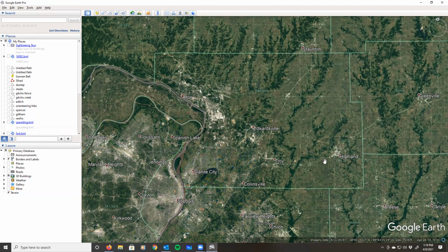So anyway, that's the basics that you need to know on state plane coordinate systems and projections. As far as the terms you need to make sure you're familiar with, there is the mapping angle, or the convergence angle, which is the angular difference between grid north and geodetic north.